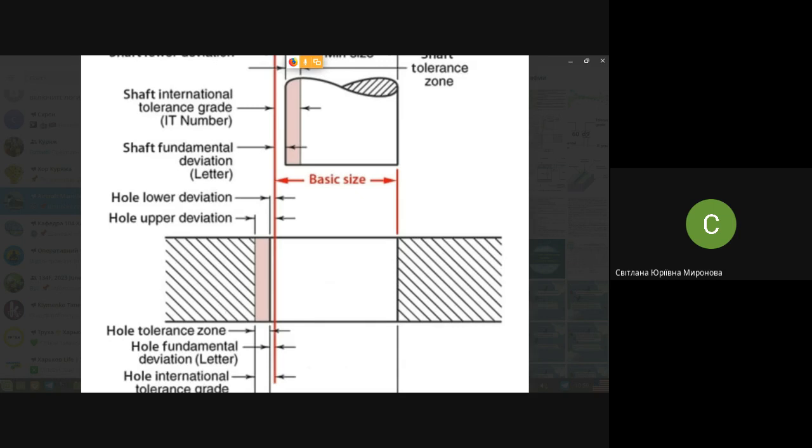What is the advantage in this case? The advantage is that during assembling, on one hand, you don't need any adjusting and you don't need any complex work. You're just attaching parts to each other. Now, you're just mating the parts, and due to coincidence of surfaces of parts, you already have some accuracy of the assembly unit. So during assembling, everything is fast, simple, and seems cheap because you don't need additional assembly tooling.